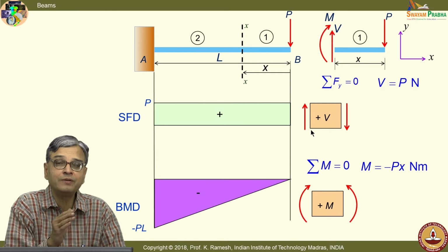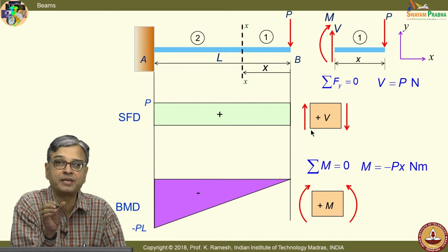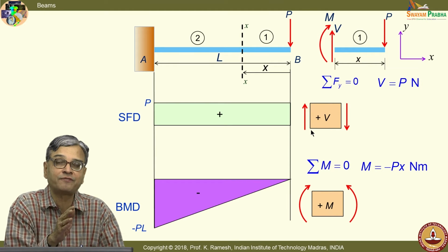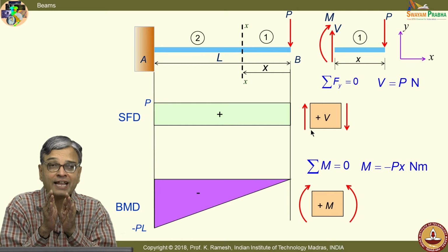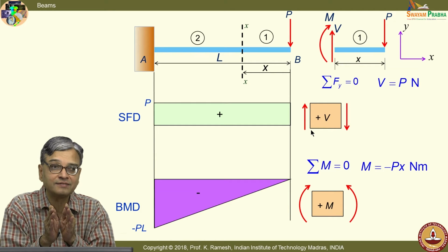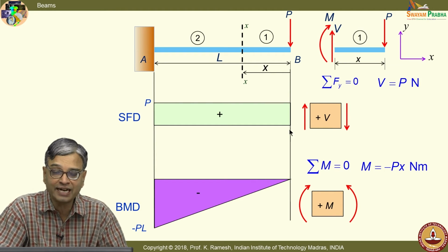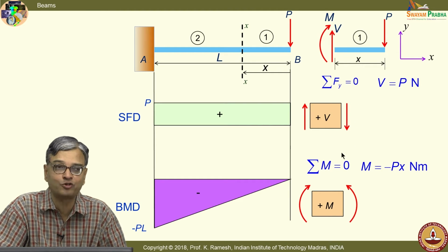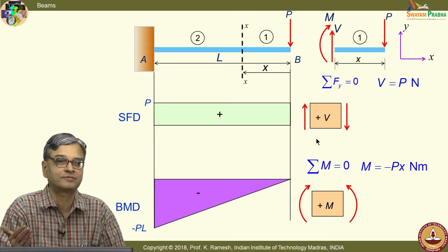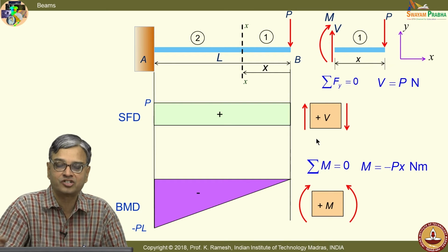See, soon we will take out a block from the beam when there is distributed loading and identify what happens in the negative surface and positive surface. There the block will have a finite length of delta x. When I write the quantities, I have to write the quantities carefully. Since you have not seen that, you do not get a confusion. Once you see this, then you will get confused on this. And this is a symbolism used in higher studies also, when you want to learn stress tensor and so on.